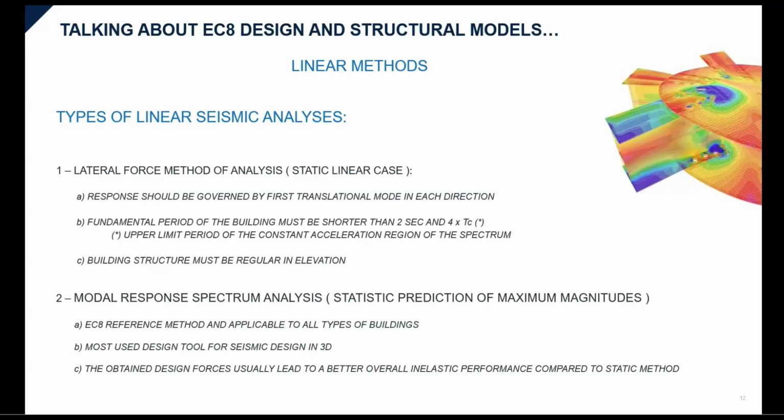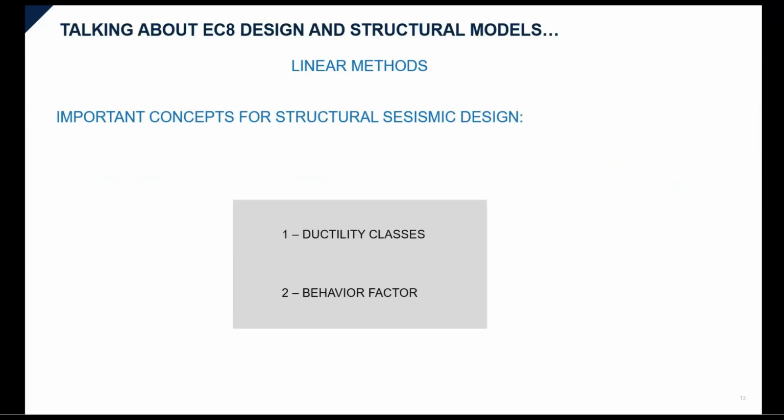On the other hand, we have another method such as the response spectrum modal analysis, which provides a statistical prediction of the maximum magnitudes of different modal quantities. It is the reference method recognized by Eurocode 8, applicable to all types of structures, and the most widely used tool for seismic structural design worldwide. In general, we obtain design forces that lead to better seismic capacity or performance compared to the equivalent static linear force method. This linear method or these linear methods depend significantly on two very important concepts in seismic analysis.